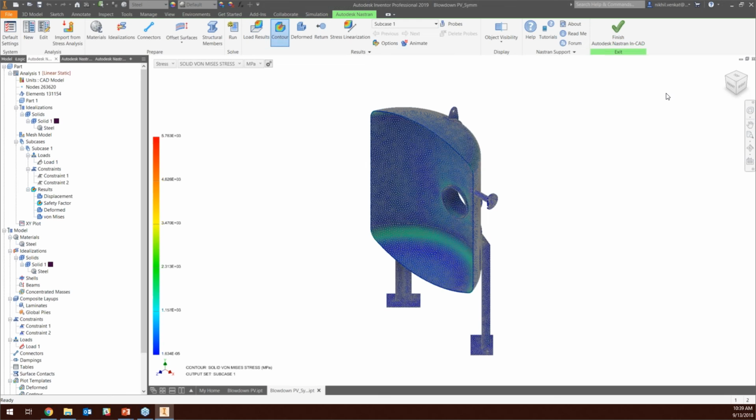Think about it, right? If you have the whole model here, you're not using half of it, your element size is going to approximately double. Or quadruple if you can use a quarter section. Exactly. Or more than that, depending on if you're doing domes and stuff. Anyways, beyond that, you're going to start increasing the amount of nodes, the amount of elements. It's going to have to calculate a lot more stuff, and then you can hear your computer chug for hours, possibly depending on your mesh sizing.